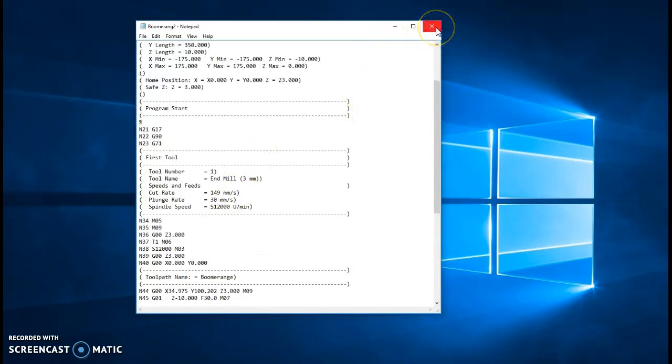So essentially the last part is you open that up in the controller software, WinPC NC, which is running on your Windows PC connected to your machine, and essentially reference the machine, set your working origin start point on the bed and click go, and it will cut it out. And then if you want to cut another one, you just replace the material and click go again. You don't need to do anything else. You just repeat the same process.